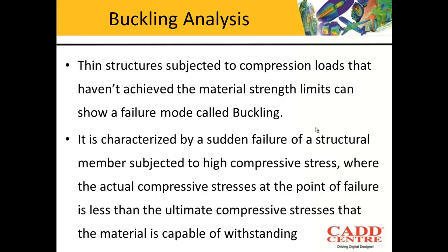Even when the actual compressive stress is lesser than the ultimate compressive stress, the material can fail, and we have to find out at what value of load this failure occurs. That entire concept is called the buckling concept.